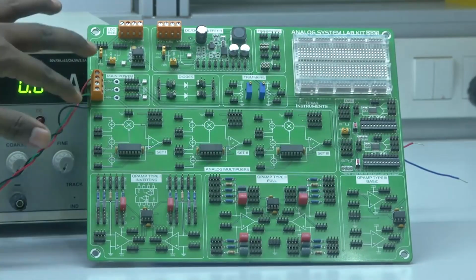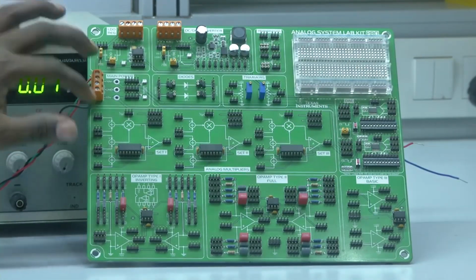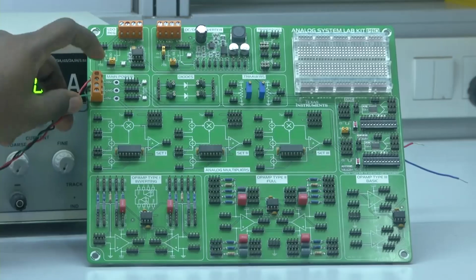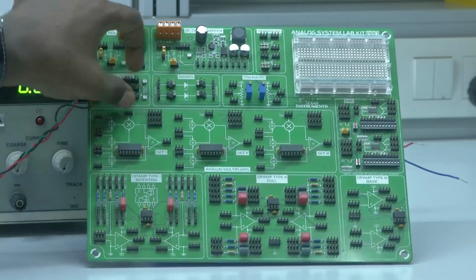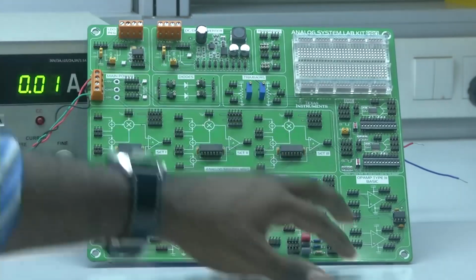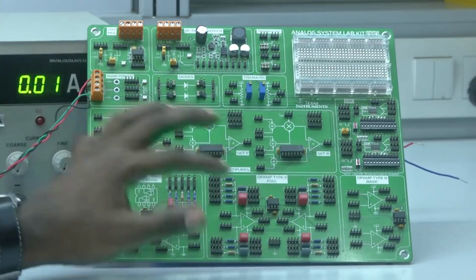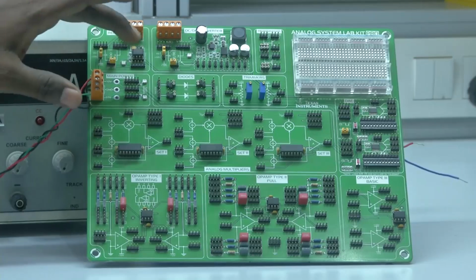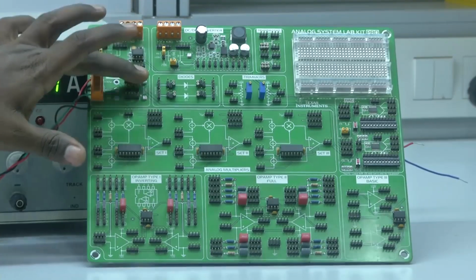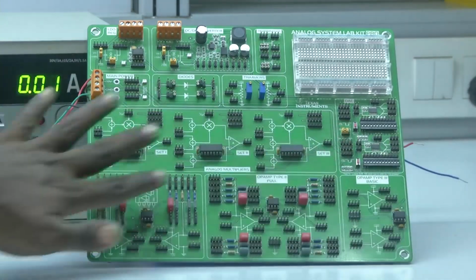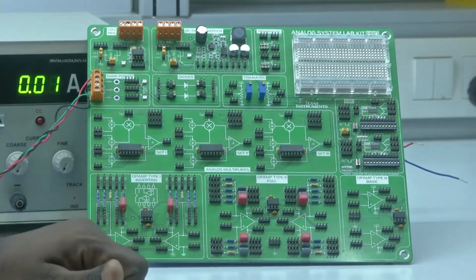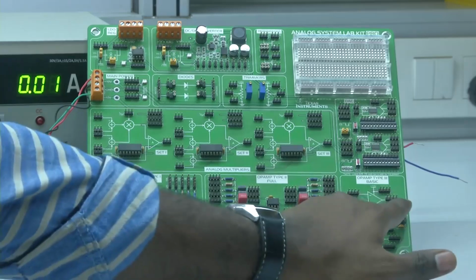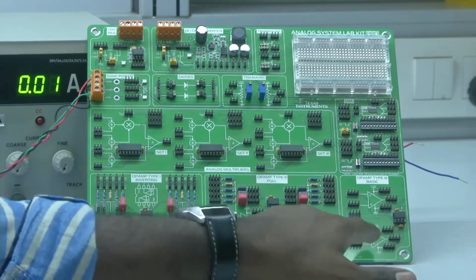Or there is also an option where, by using a main power, providing plus 10, minus 10 and ground, we can either access the power using this board, or it has already been internally routed for connections from this to power all the operational amplifiers as well as other circuits available in the board. In order to tap the output voltages, again they have provided banana connectors.